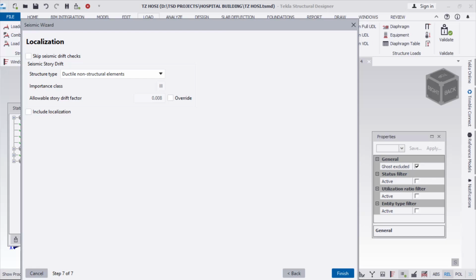For example, when you talk of low ductility, sorry, the brittle structural element, the first one here, that is to tell you that it is a structure with a low ductility. That means it has a very low capacity to dissipate the seismic energy. And in this case, we are likely to have the structure collapsing suddenly.